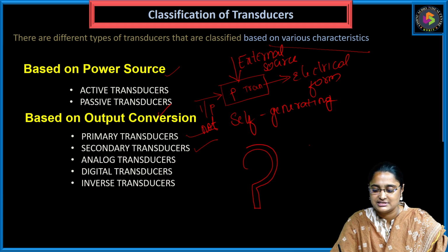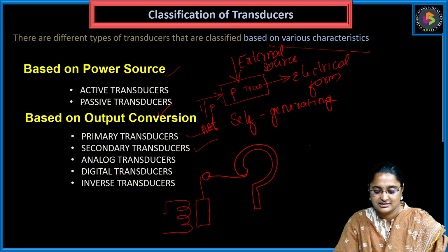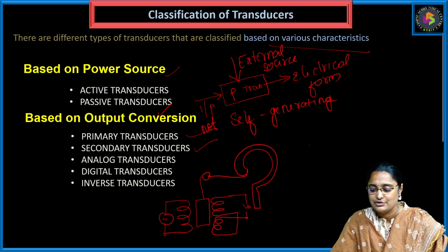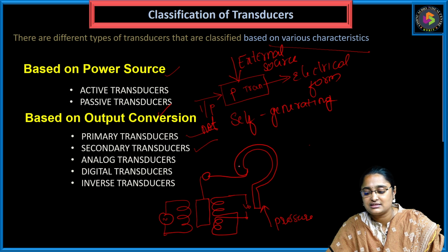It is a C-shaped structure connected to a pulley, which is then connected to the core of an LVDT, which has an excitation source coming in, and a series opposition circuit where you measure the voltage. When I apply some pressure, there is a deformation in this tube, right?